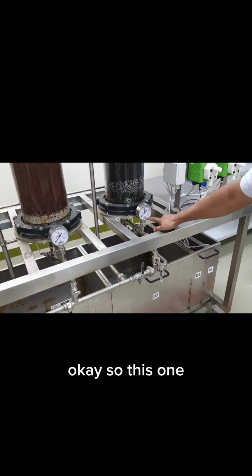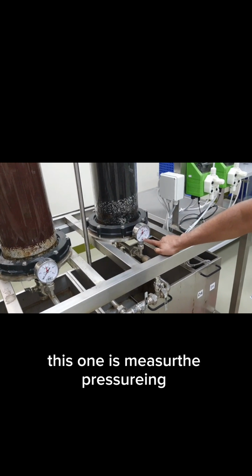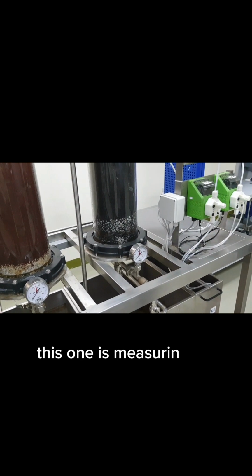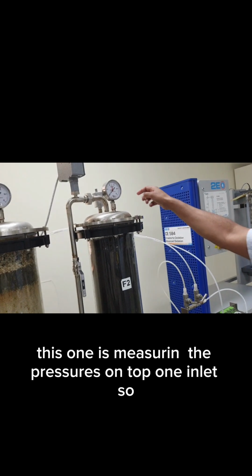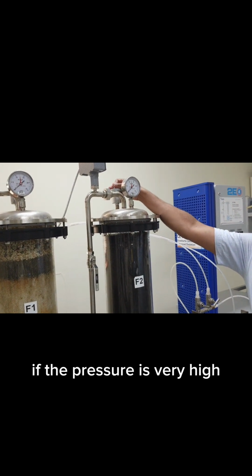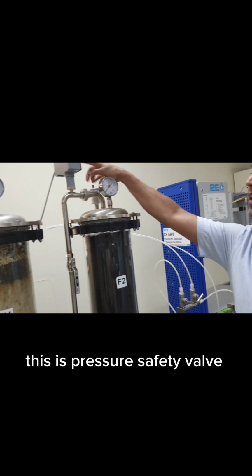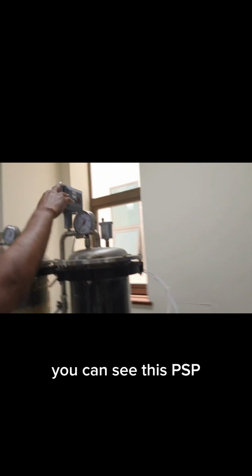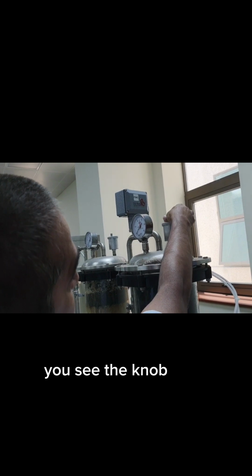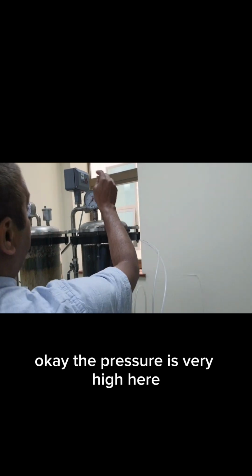This one is measuring the pressure in the outlet. This one is measuring the pressure on the top one, the inlet. So there is a pressure knob up there. If the pressure is very high, there is a pressure safety valve on the top. You can see this PSV, safety valve. So it is controlling the pressure. If the pressure is very high, you see the knob. You can release it a little bit.